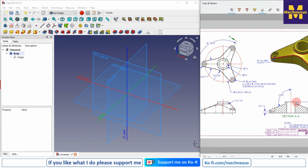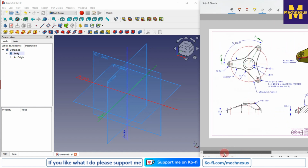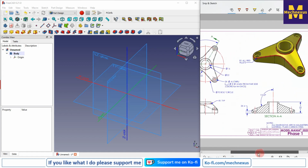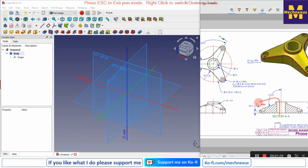The outer one is 22, and this angle is 120 degrees, and in this view we have the height. So what we will do, we will first create this profile, and then we will revolve it 360 degrees along this axis.